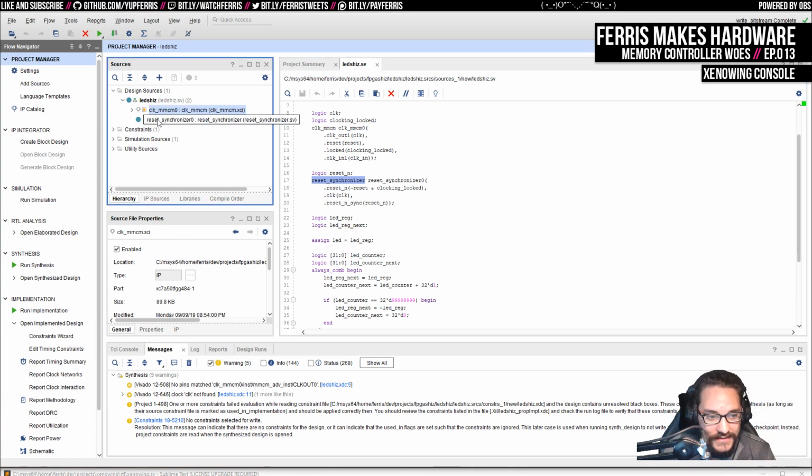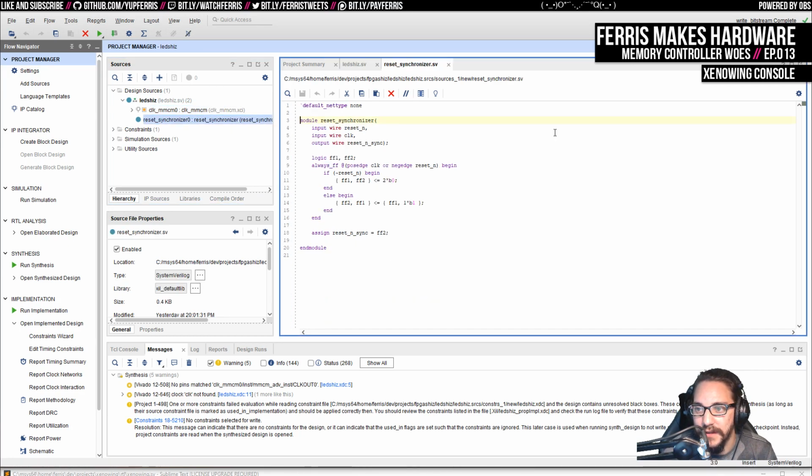So with FPGAs, I actually don't think you always need to have a reset functionality at all. If you know you're targeting a given FPGA, you don't necessarily need to use the reset, because you can always power cycle your board. So this is not necessarily something you have to look into, but I think it's a good idea to design that way anyway, because having resets like this is good if you want to do some simulation. And if any of this ever moved to ASIC, obviously you'd need some kind of reset stuff.